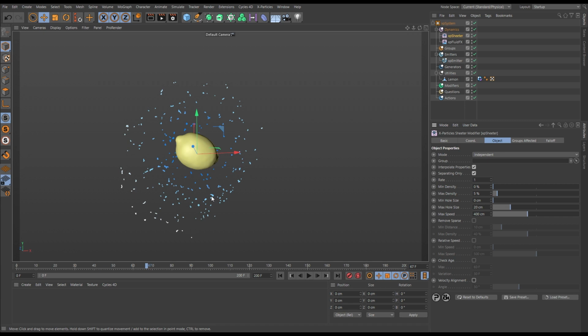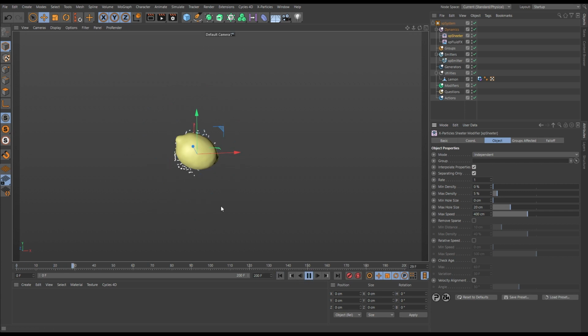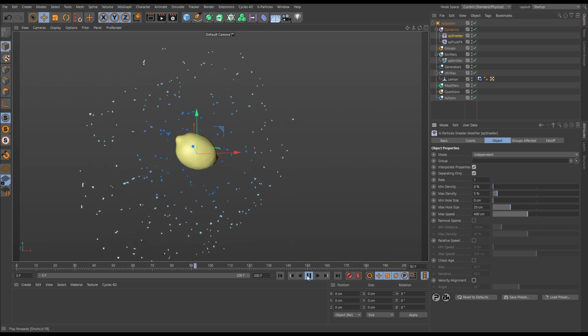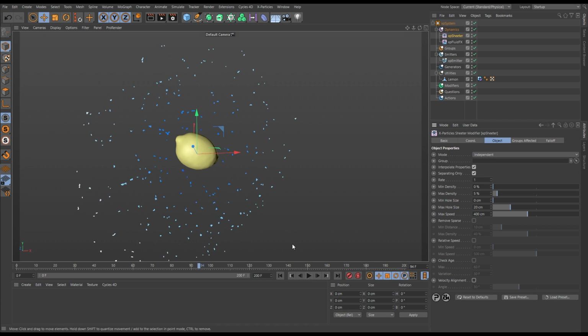So what that means is, if we have it set here, it's only going to sheet particles if they've got a very low density value. So that's the particles on the outer edges of a fluid body, the ones that haven't got lots of other particles close to them. And because we have this density value set so low, it's basically disqualifying the majority of the particles in this simulation from being able to sheet.